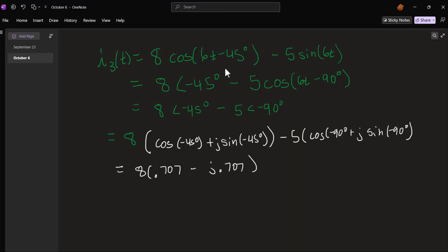And so the equivalences are that the resistance remains the resistance. So resistance is real and resistance is always R. L in the phasor domain becomes jωL, where ω is the angular frequency and L is the inductance. And for C, it's 1 over jωC, but I usually use, instead of 1 over jωC, negative j over ωC.